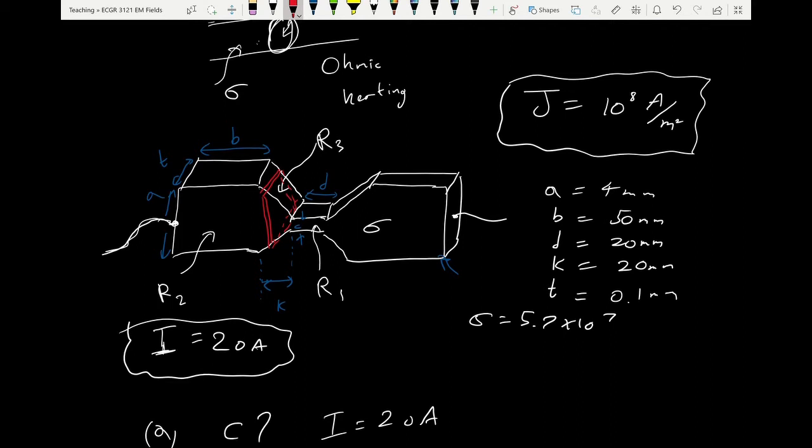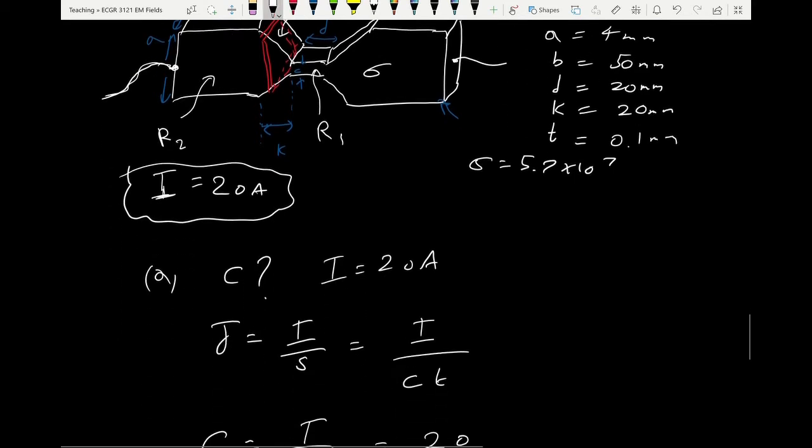Because integration is just summation, and each one of those slices is connected in series to the next slice. So I'm effectively finding an infinitesimal resistance for a small slice, and then adding all the slices together, looking at it as an infinite number of series-connected resistances. That's the way you calculate the resistance for irregular objects.